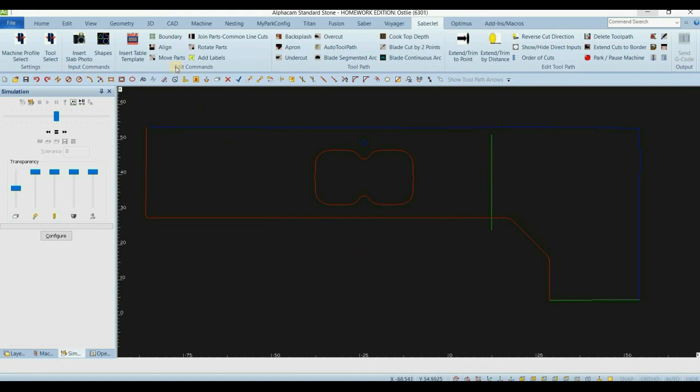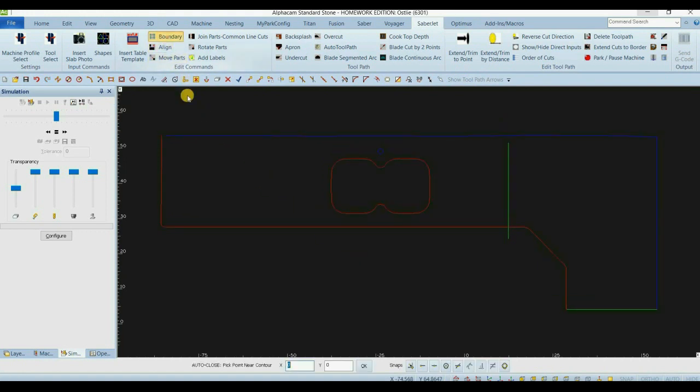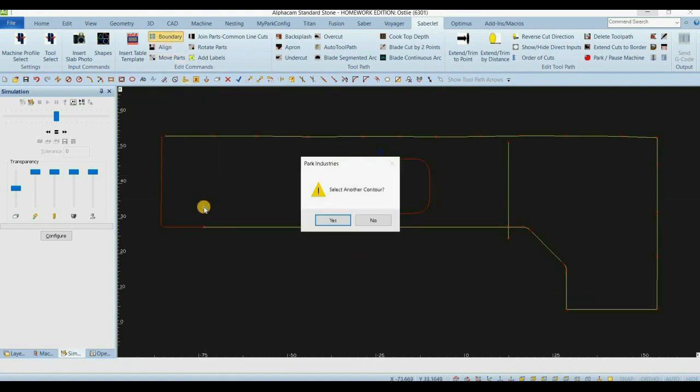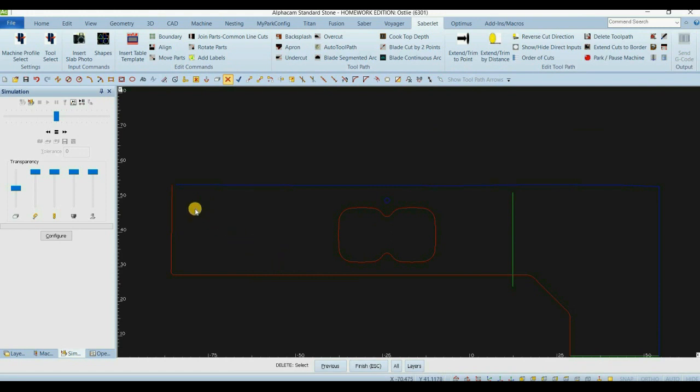When selecting contours, if the entire boundary is not copied, or seams are not recognized, there is something wrong with the original drawing. It is possible that there is a gap greater than 1/2 inch, an extra line under a line, or the seam line does not touch or bisect the perimeter.